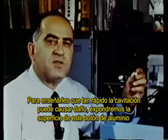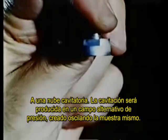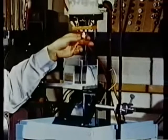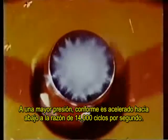To show you how quickly cavitation can cause damage, we will expose the surface of this aluminum button to a cavitating cloud. The cavitation will be produced in an alternating pressure field created by oscillating the specimen itself. The specimen is driven by this magnetostriction oscillator. We are looking directly upward at the face of the specimen. The total amplitude of vertical oscillation is only 0.02 of an inch, but the pressure is changed from below vapor pressure, as the button is accelerating upward, to a high pressure, as it is accelerating downward, at the rate of 14,000 cycles per second.